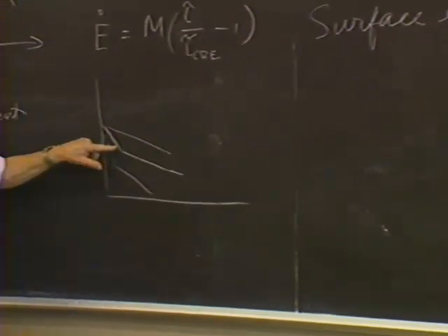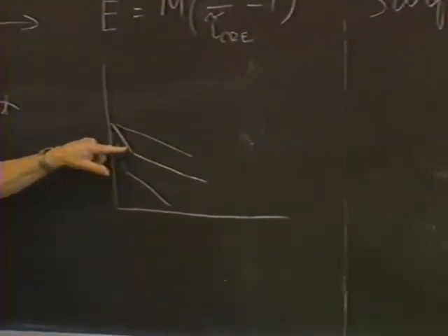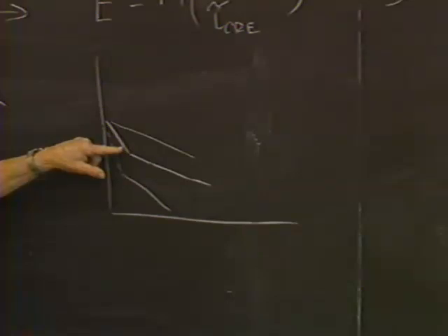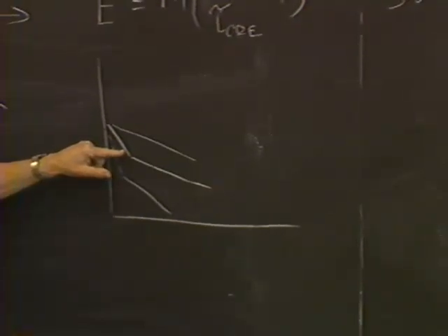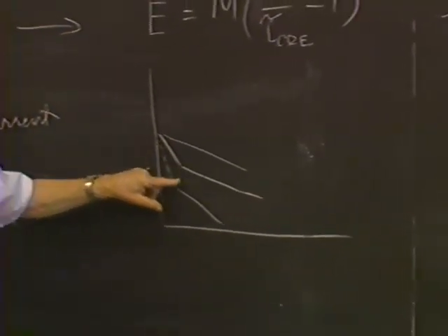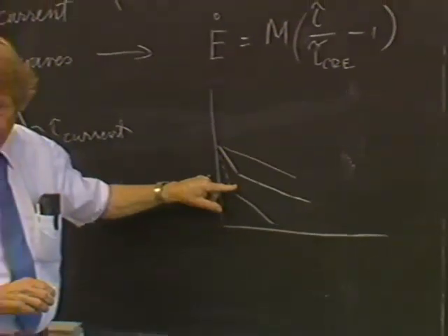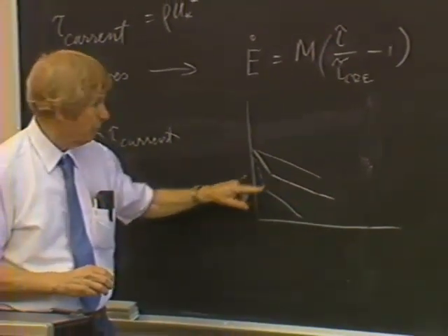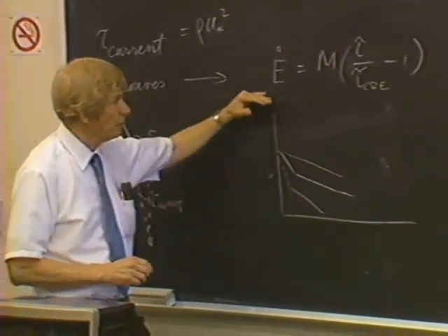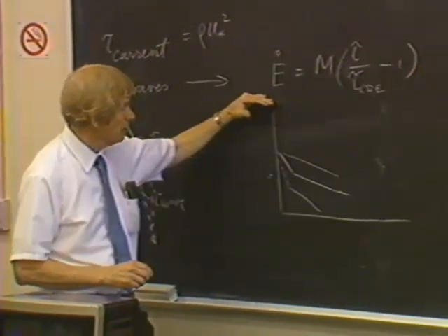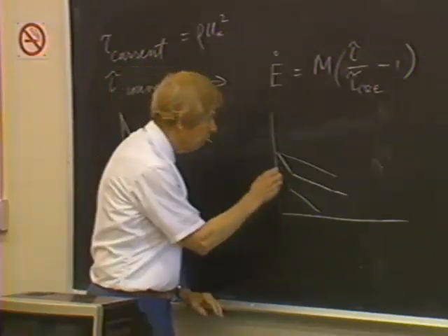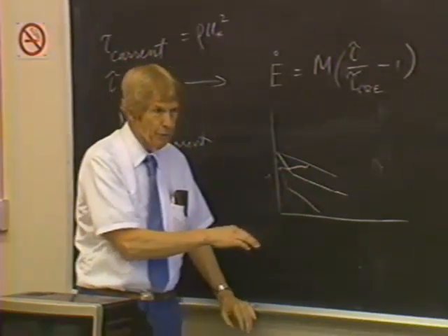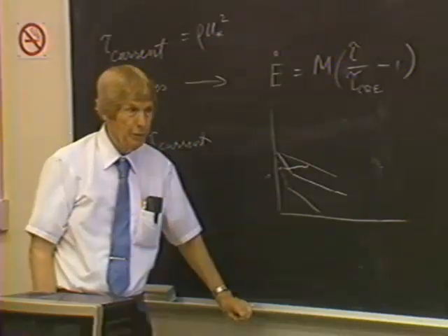There's also a handout, which should have been discussed in the videotape, describing Mehta and Partheniades' measurements showing changes in critical shear stress with depth. This is for surface erosion. If the shear stress exceeds the bulk strength of the material, however, it'll just erode immediately down to the depth where that strength equals the applied stress.